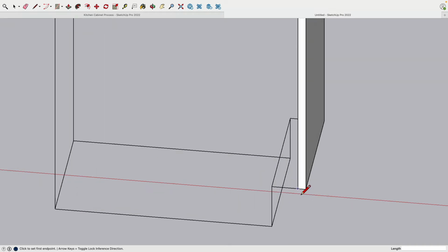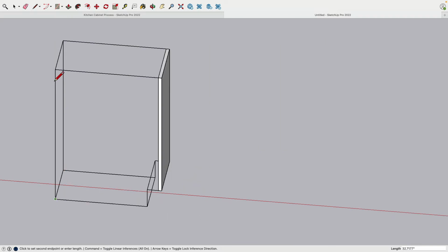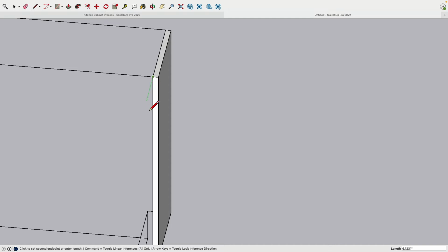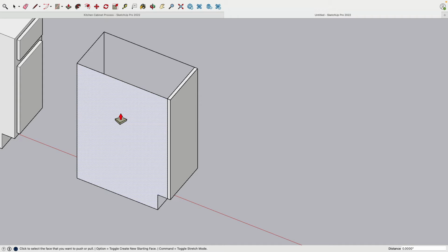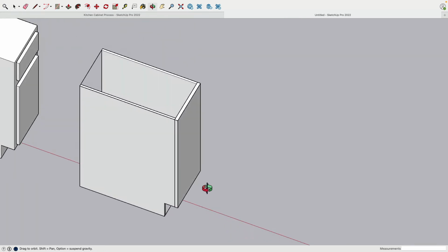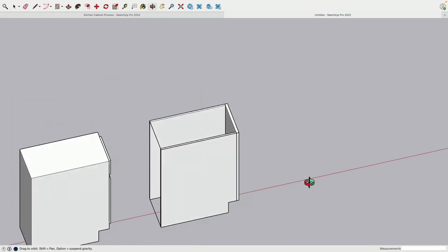Here now, it's not there, but from here I can start drawing myself a nice side representation there. Very good. And this piece has a material thickness of 0.5 of an inch. Triple click, right click, make a group, and then make a copy with the move copy command combo. Beautiful. You see now it's actually not too complicated.